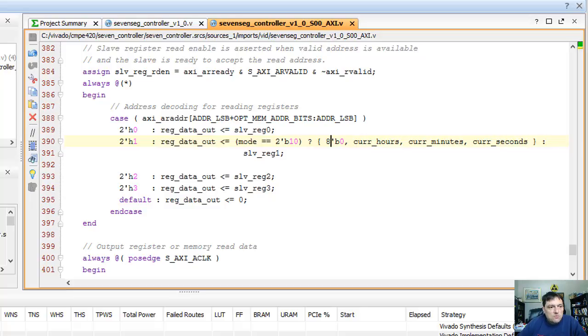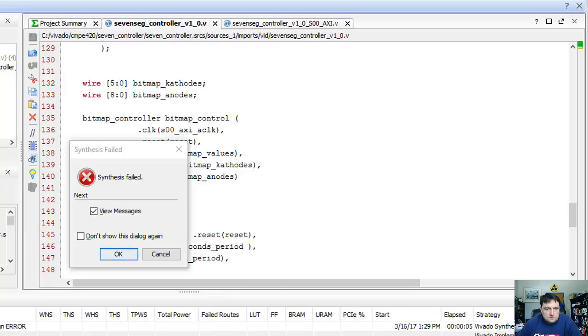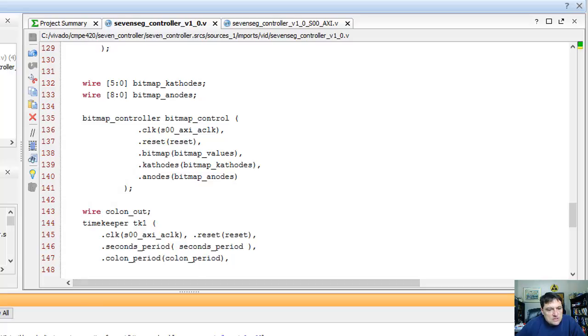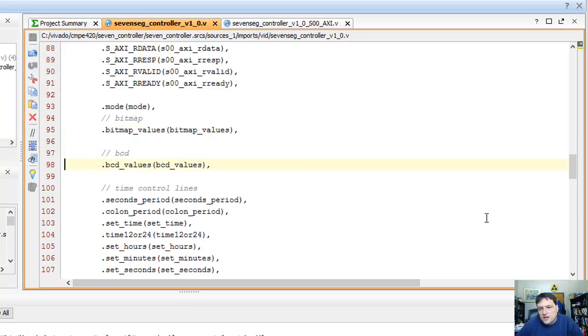Now, one of the things I want to do in this video is to go through as far as the synthesis to make sure that I don't have any errors in my code. So alright, I kind of expected an error. Synthesis finished and it comes back and says view messages. So if I go back and view the message, it says well, that's not the error I expected. So I have a duplicate port. And we'll go ahead and synthesize again.